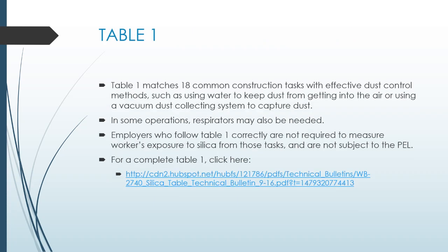So Table 1. Table 1 is a pretty inclusive table that has 18 of the more common construction tasks, and looking over it, there's not too much that we do outside that table. And it lays out the effective dust control methods. It tells us the type of tools we have to use and the PPE we have to wear while doing it. It tells us whether or not we have to wear respirators. And if you guys remember correctly from our respirator program and fit tests, the respirators we use do protect against silica dust.